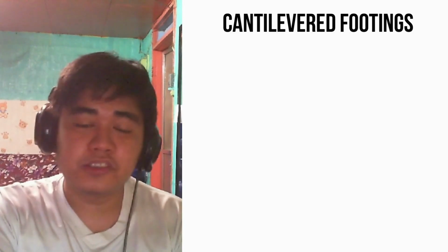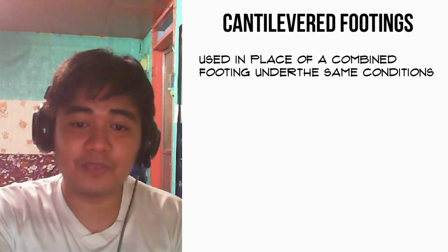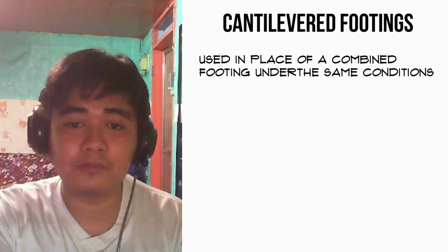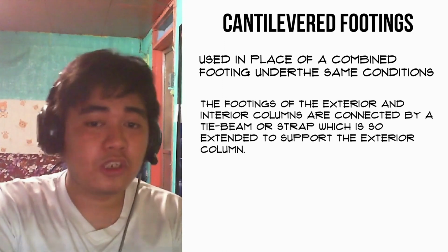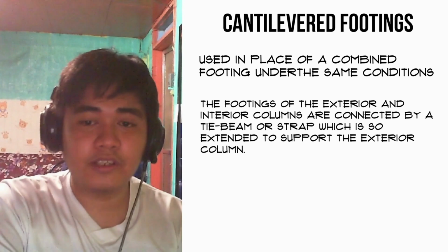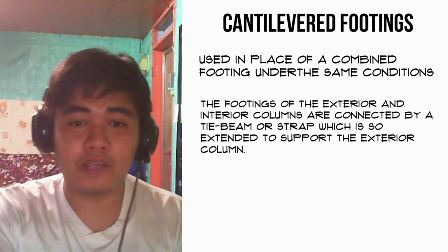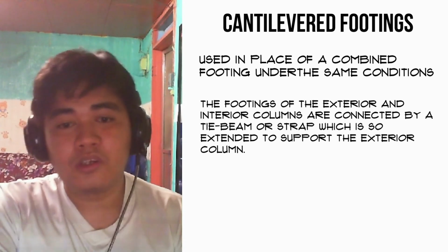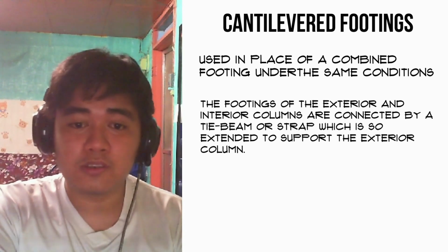Cantilevered footings. This type of footing may be used in place of combined footing under the same condition. In this type of construction, the footings of the exterior and interior columns are connected by a tie beam or strap, which is extended to support the exterior column.